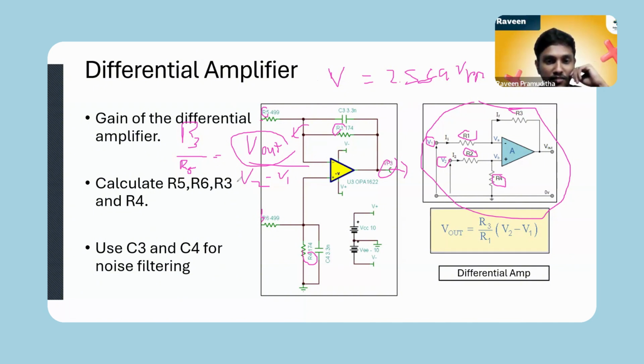And V2 minus V1 is the swing voltage of the output from my transimpedance amplifier. I found that swing as 1.85. Yes, this is the difference between these peaks.